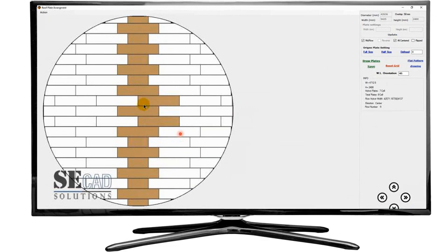After that, you can modify it, like dividing the plates or rotating the blades from the horizontal position to the vertical position, and making splits on plates, and defining the width of each plate. Okay, defining the orientation of the welding lines of the plate.